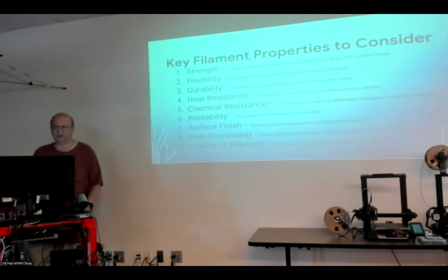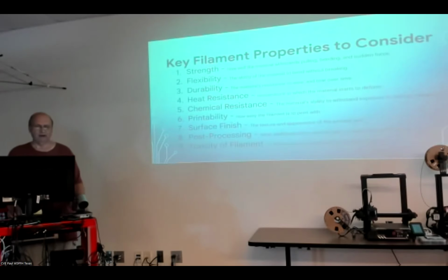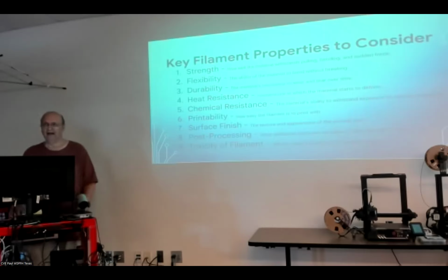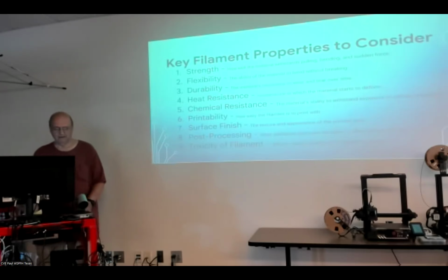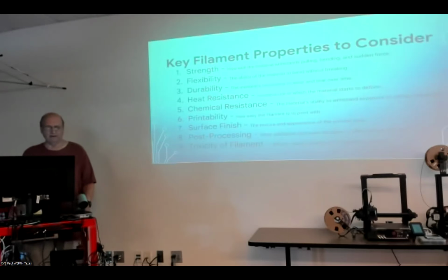Probably not too concerned about that one for anything that I might make. No, but if you're printing stuff to go under the hood of your car, which I know people do, chemical resistance and heat resistance are two big factors. Printability. That would be PLA, the easiest one as far as printability. What kind of surface finish does it give you? You know, is it smooth or is it jaggy?